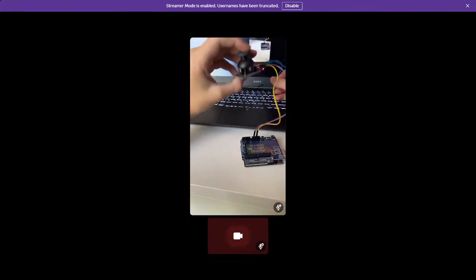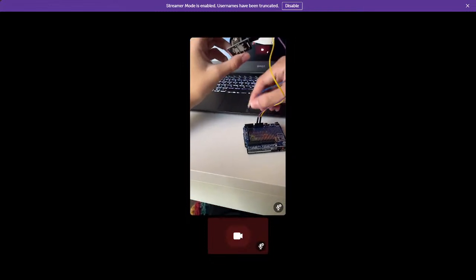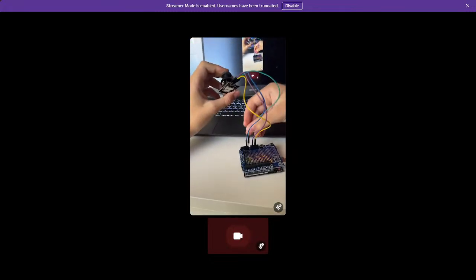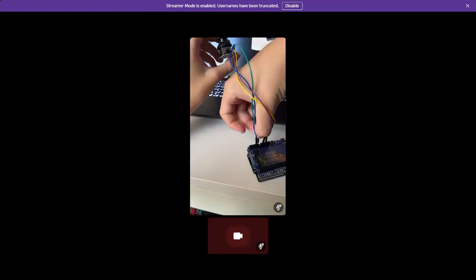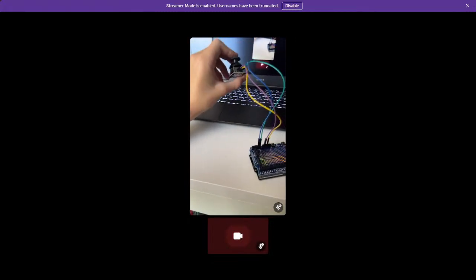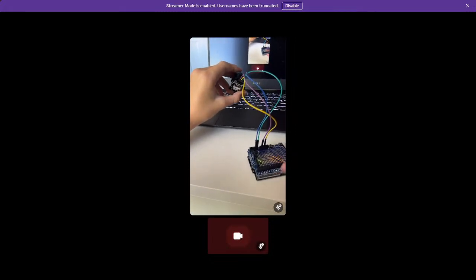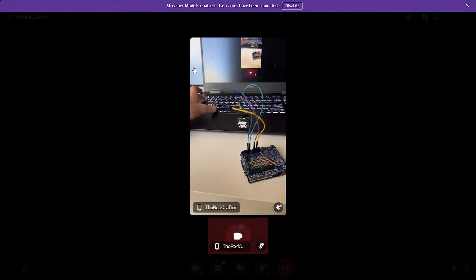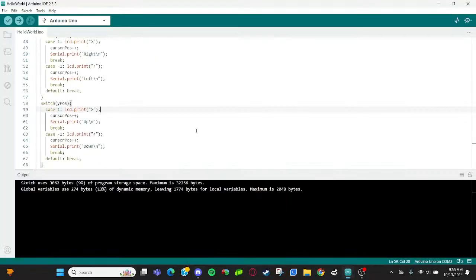Analog is this X. This is the Y pin, so it's going to go to analog 1. And this is the X pin, so it's going to analog 0. Okay. Now I can press the reset button. Hopefully it's zeroed in. And I'm going to switch back to our coding tab. Not bad.